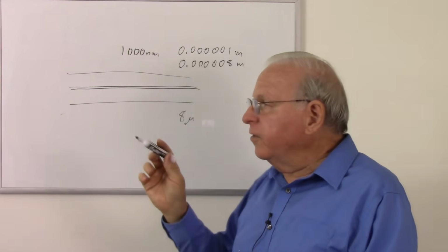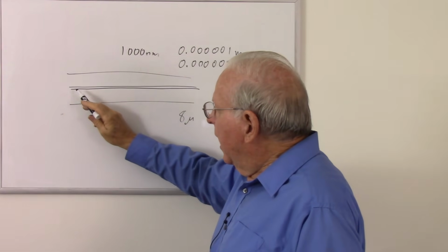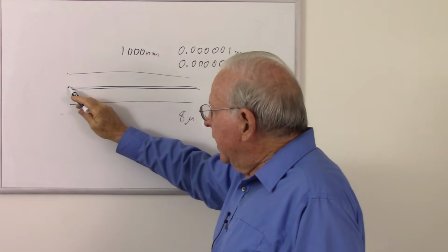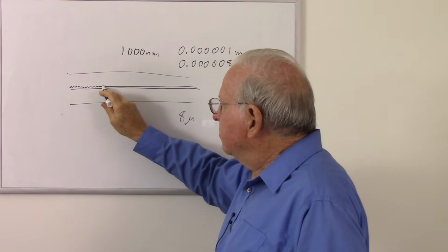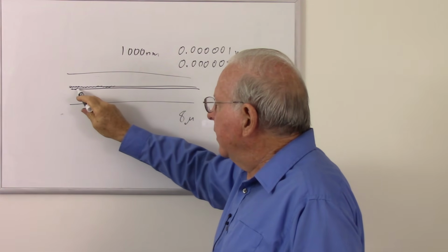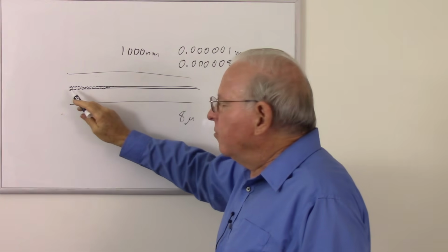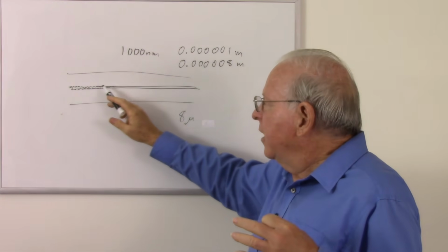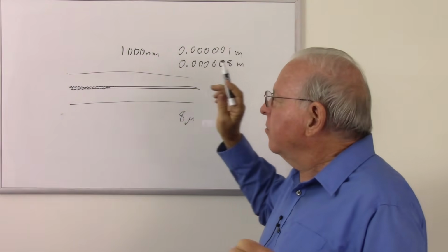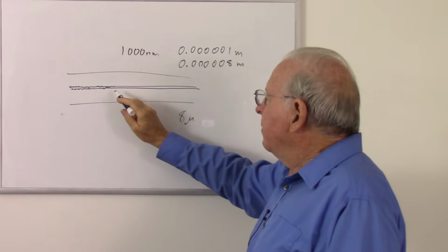And we get a whole new phenomenon when this happens. Now, what happens is that the energy begins to travel down the fiber as an interaction between the core cladding interface. And we do not have any more of these reflection modes or these paths down the fiber. We have simply one. This is called waveguide mode propagation.